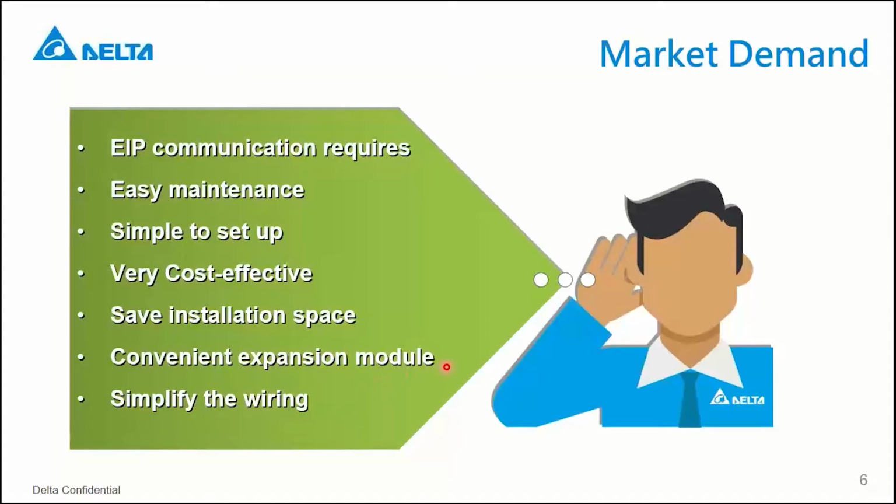expansion of the module. I think this is also very important, because before, for the end user to understand how to do the extension of the module was a little bit not so easy, because there are some settings and you have to select the input and output. But for the DTM there will be no problem with this issue. And also to simplify the wiring, because right now we use the new design, so no more screws. We just press and insert the cable. That's all.